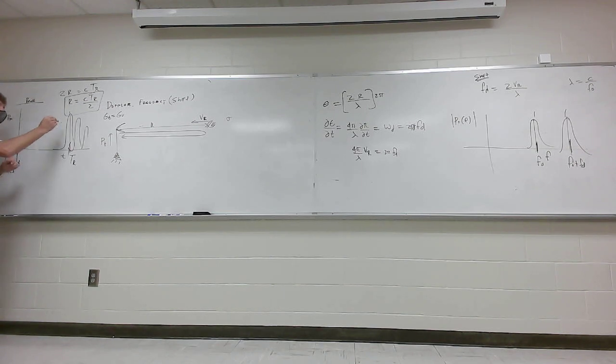Now the first peak here has to be the direct range, right? Because it's the shortest possible time. That will give you the actual range, or the time delay to the target. But this kind of stuff can happen. Y'all follow me on that? It's really bad when you've got any kind of canyons and stuff like that, where you've got a lot of ridges and things. You can get a lot of problems with ground bounce.